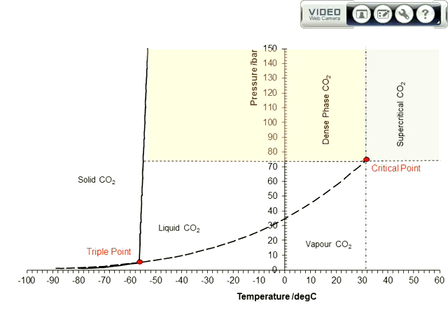But remember, you've either got to decide we're going to operate as a dense phase pipeline, which means you've got to be above this pressure, taking account of all of the code requirements for controlling pressure. So you need to look at the pressure definition diagram in PD8010, and you've got to say, right, it's telling you you're going to have to set an MIP, which is going to be 10% above your operating pressure, and then you need to think, can I actually operate at this pressure? And of course that depends on what the design factor is. You calculate the design factor and check.